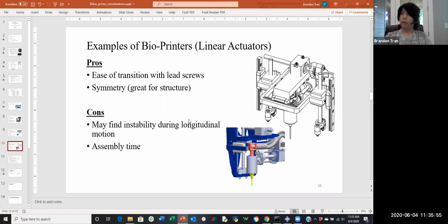The reason I designated that right now is because if you can see in this rotation right here, there's not much support holding it. So we have a big moment arm happening, just dangling out on this area. If they had something like this, which is a wedge support to hold it horizontally, then it'd be less susceptible to possibly tipping over. But other than that, they did not include that. So there is some instability that might happen in that direction.